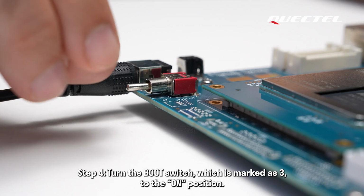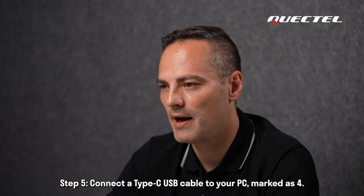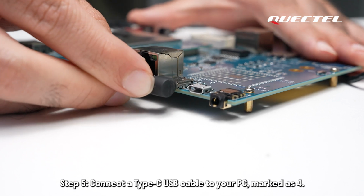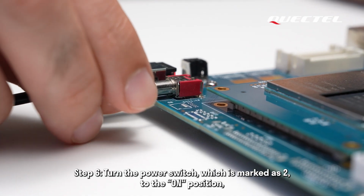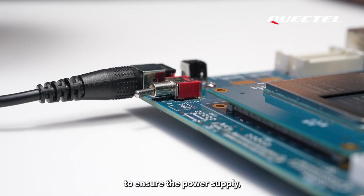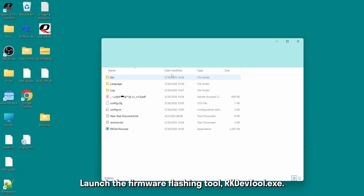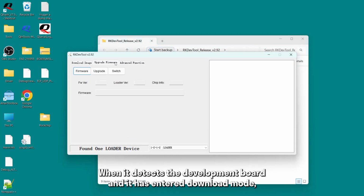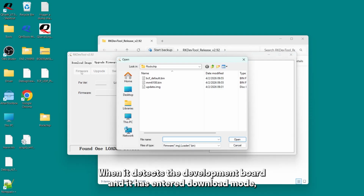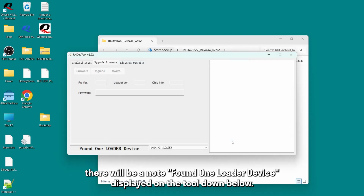Step 4. Turn the boot switch to the on position. Step 5. Connect a Type-C USB cable to your PC. Step 6. Turn the power switch to the on position to ensure the power supply, and then press the power key button to enable download mode. Launch the firmware flashing tool, rkdevtool.exe. When it detects the development board and it has entered download mode, there will be a note "Found one loader device" displayed on the tool down below.